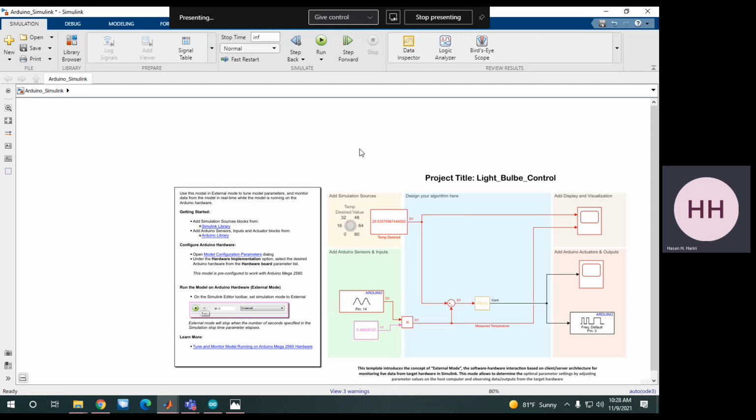Of course, more tuning will make our system maybe better or worse. So the tuning is always there; there is not just one value for PID. Of course, there are many. In this new session, it's about controlling the same system, but here with MATLAB. So what is the advantage of MATLAB over Arduino? Mainly, at the first point, it's a new platform, so you know how to program your Arduino using MATLAB.